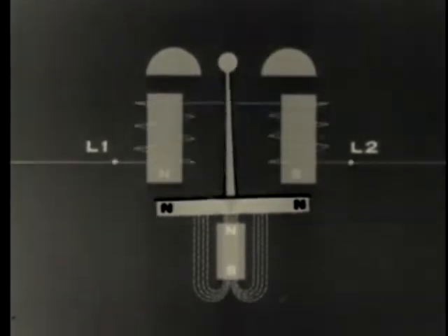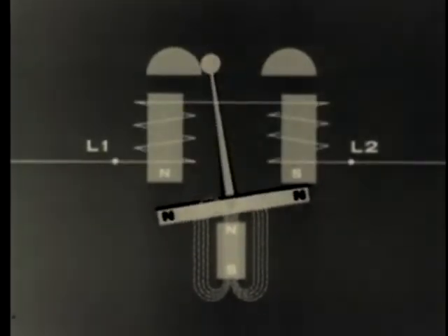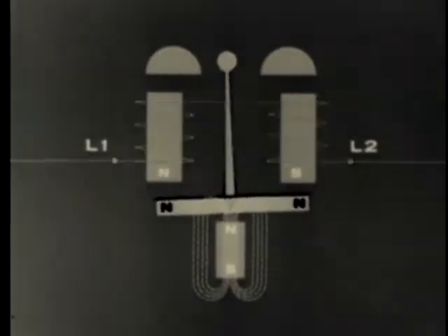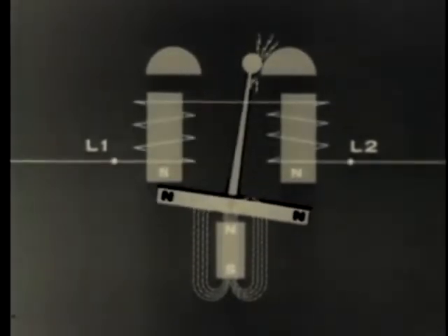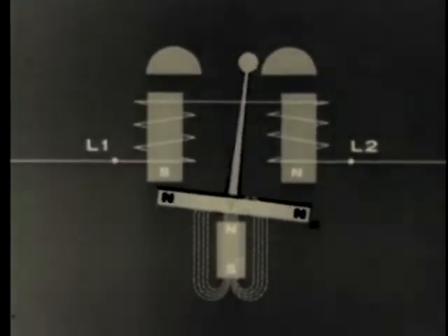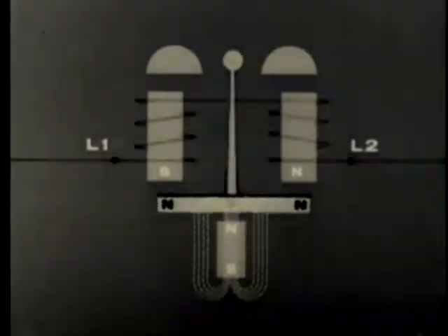When a signal is sent over our line, the polarity of our electromagnet will alternately attract and repel the ends of the armature operating the clapper rod, which alternately strikes each gong. Here we see an actual telephone ringer in operation.